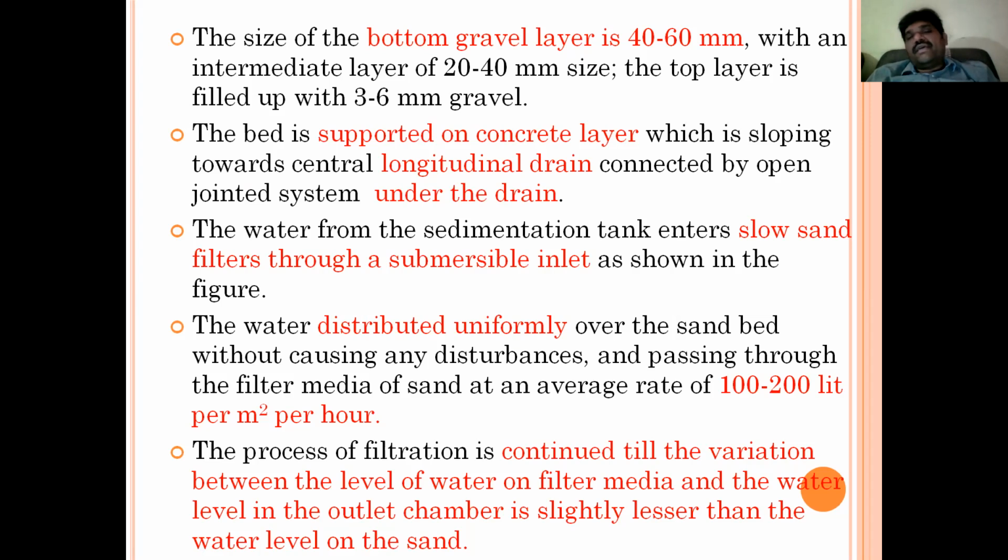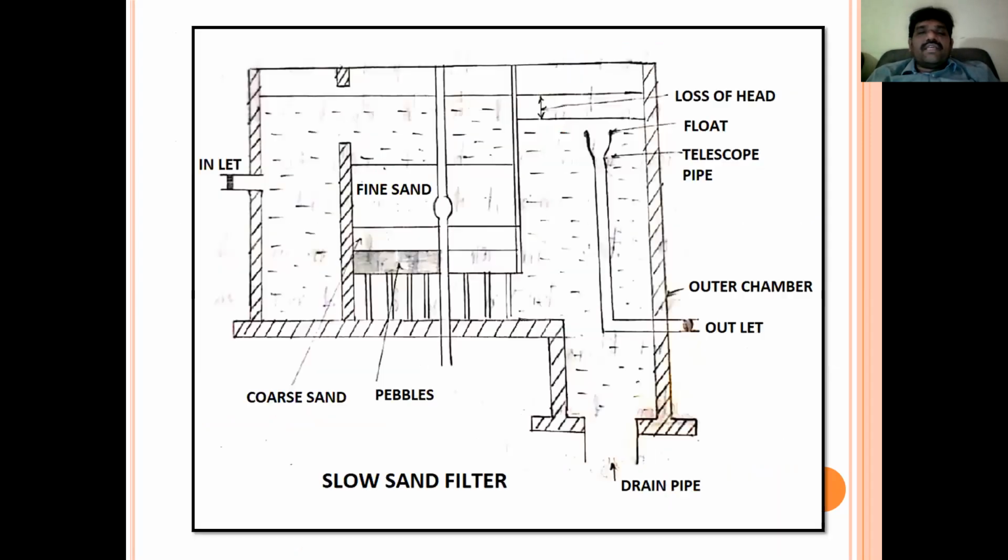The water is distributed uniformly, and through this step water enters into the next chamber. The difference between the water level in the inlet chamber and the water level in the outlet chamber gives the information of loss of head.